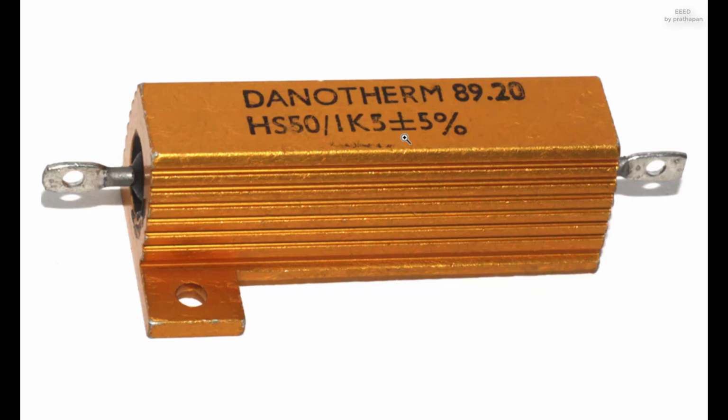Discrete resistors in solid-state electronic systems are typically rated as 1/10, 1/8, or 1/4 watt. They usually absorb much less than a watt of electrical power and require little attention to their power rating. Resistors required to dissipate substantial amounts of power, particularly used in power supplies, power conversion circuits, and power amplifiers, are generally referred to as power resistors. This designation is loosely applied to resistors with power ratings of 1 watt or greater. Power resistors are physically larger and may not use the preferred values, color codes, and external packages described below.